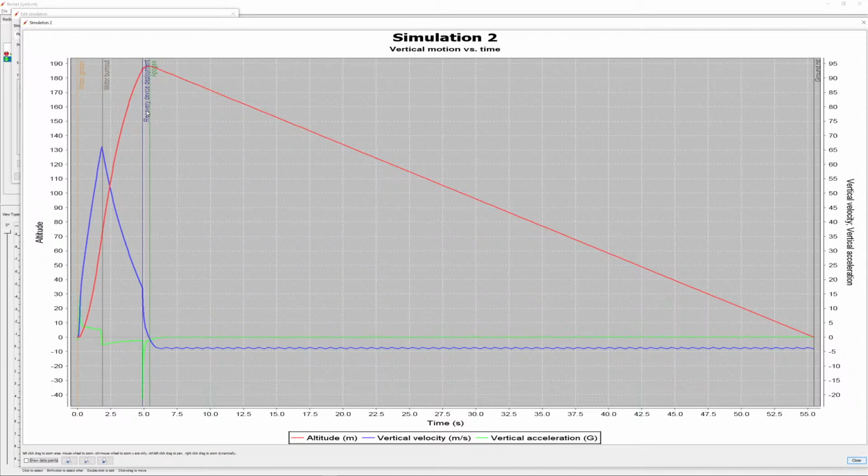And so the parachute kind of got pushed up against it and then stayed there. So when it flipped over and started falling nose first, the nose cone fell off due to weight, but the parachute didn't have gases hitting it and trying to push it out, because it had tried to deploy before apogee and not work. That's kind of what I'm thinking the problem with that flight was.